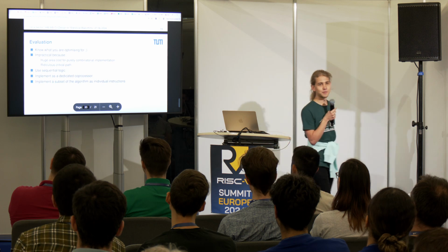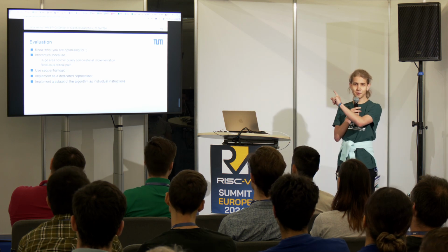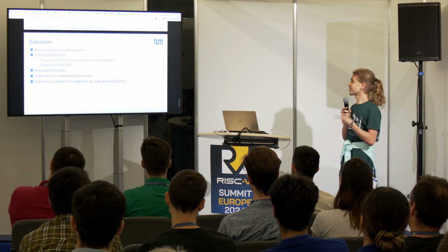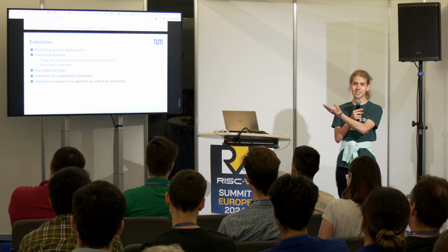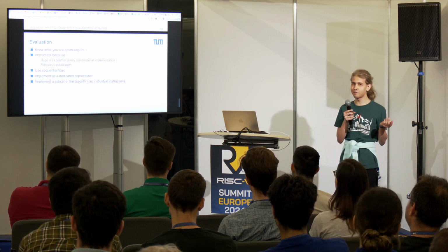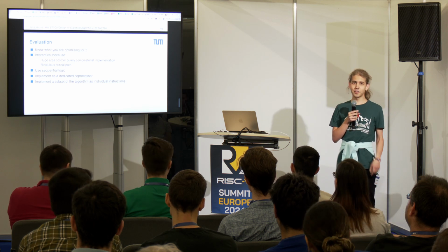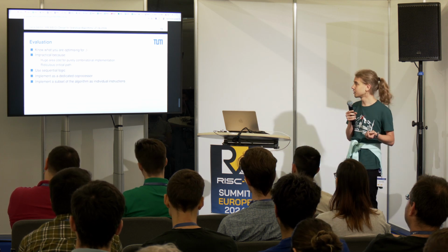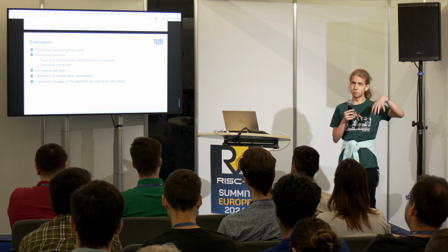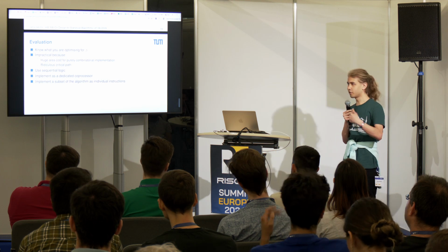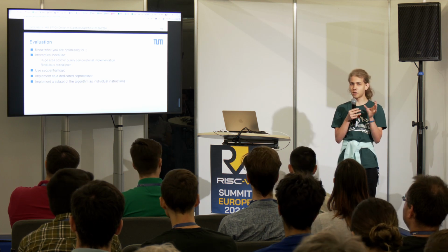All right, so what did I learn from this? The most important part is to know what you're optimizing for. We were told to optimize the cycle count, not the runtime, not the area. So that's what I did. Obviously, this implementation isn't actually practical, because if you would implement this with combinatorial logic, the area would be huge. You would have a terrible critical path, and you'd have to slow down your entire processor for that. However, you could implement it with sequential logic, which would make it slower and, in practice, take more cycles. But then, in turn, you could take this whole block, implement it as a coprocessor, and kind of like we have DMA engines, let it run over the data that's in memory while your actual core does something else.